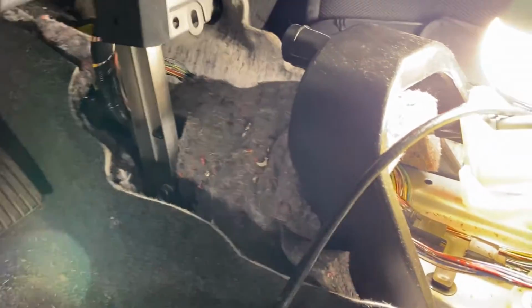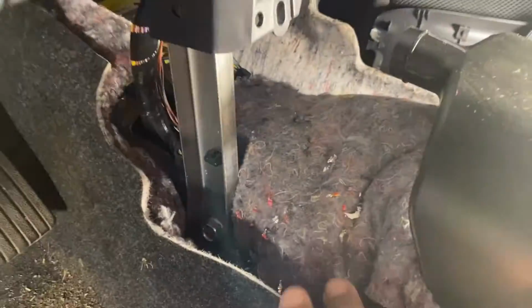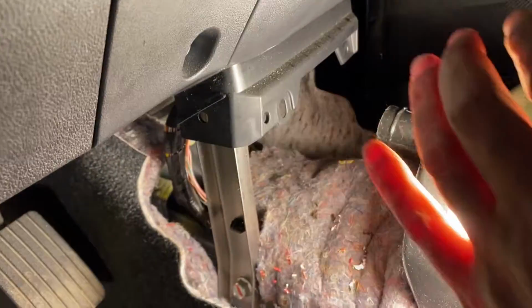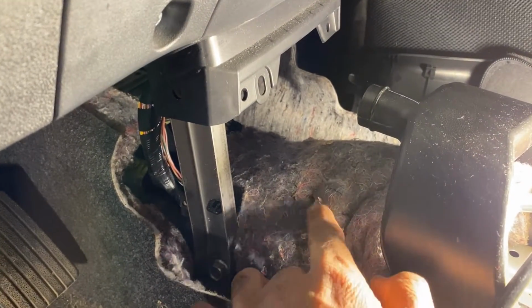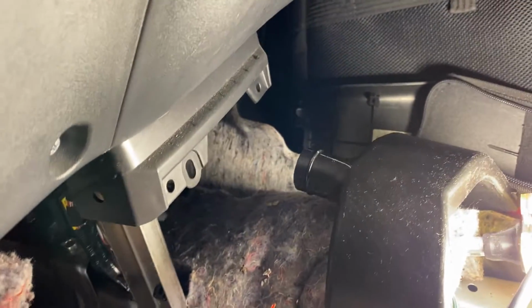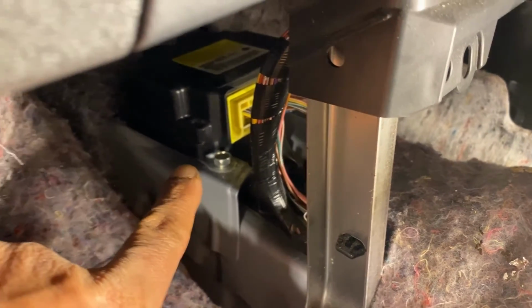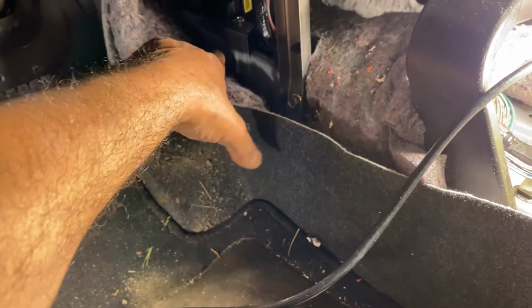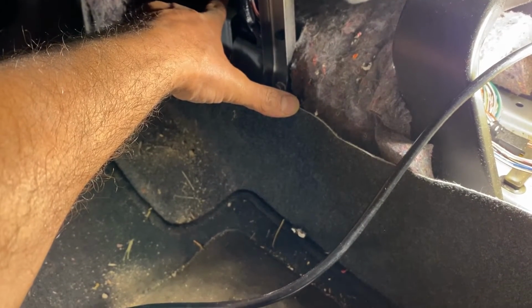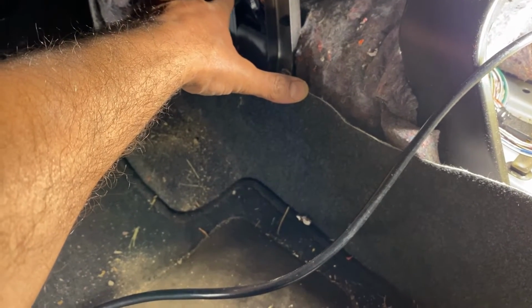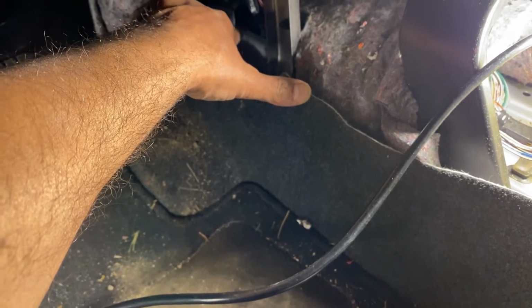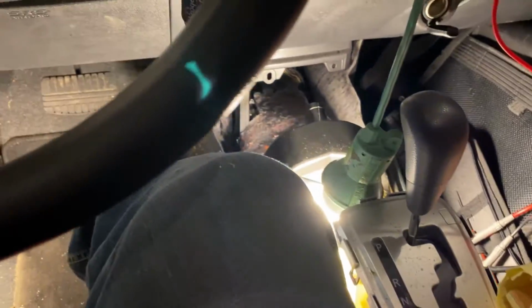But I noticed something. This car was sitting, it looks like the customer parked somewhere where I can see this little confetti, and it looks like mice got in here. So I'm not sure if there is a wire. Anyway, I'm going to take the airbag module out if I can't figure it out, because in most Japanese cars the airbag module and the ABS have the end resistor, the terminal resistor for the CAN bus. So we're going to go ahead first and measure the resistance.